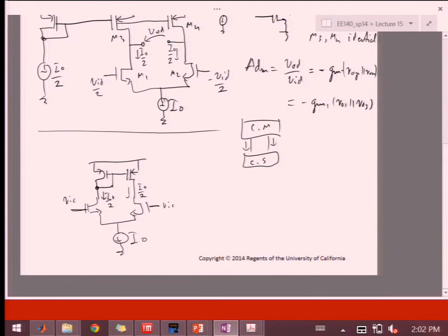Okay, so this thing has this kind of imbalance over here, in the sense that the load is different. But if you look at what's happened at the tail, neglecting R naughts to the first order when you're looking at current distributions, because 1 over GM is so much smaller, you can apply the same bisection principles that we talked about.